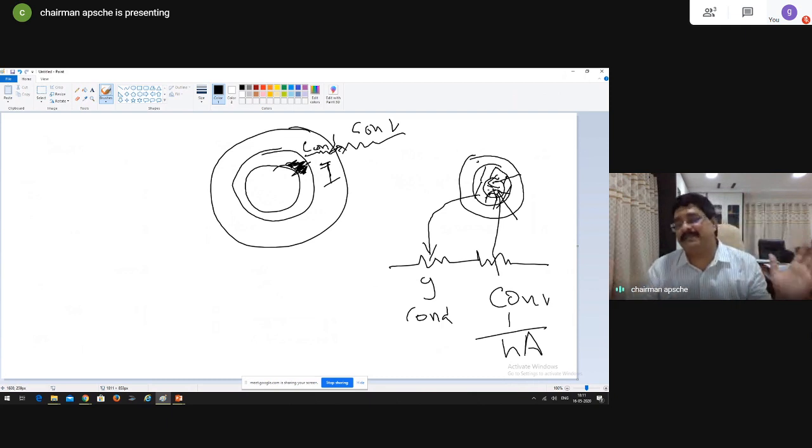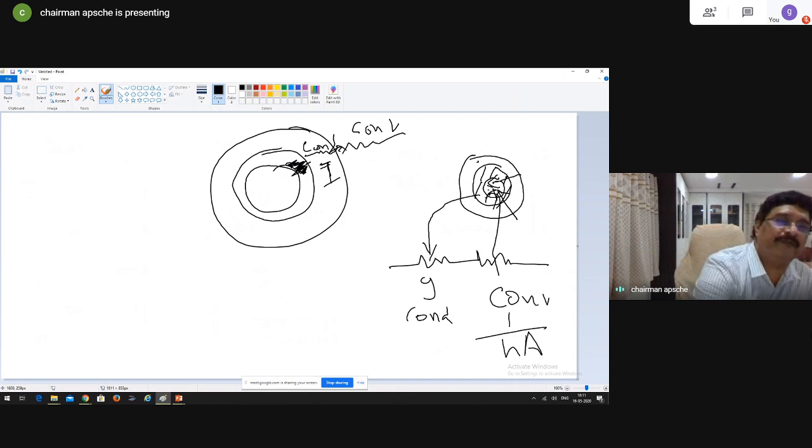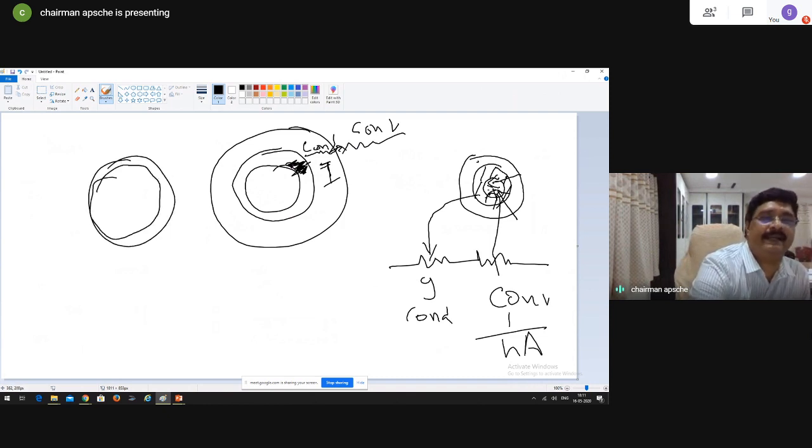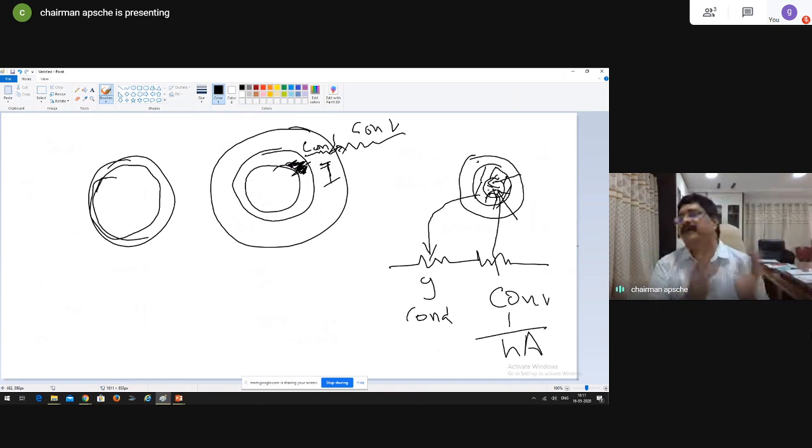When both resistances increase, obviously heat transfer is reducing. So internally, inside a pipe, if you start adding insulation inside it, the effect is only to reduce the heat transfer. Heat transfer cannot initially increase and then decrease. That happens when you add insulation outside the pipe.